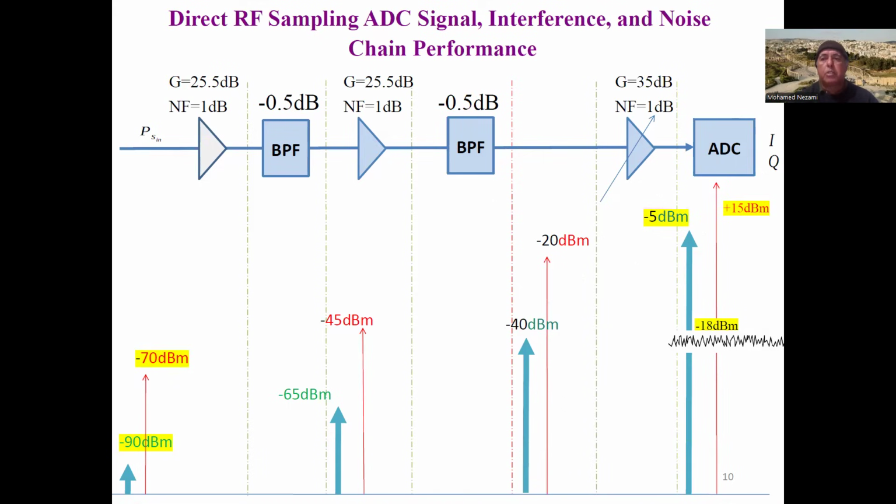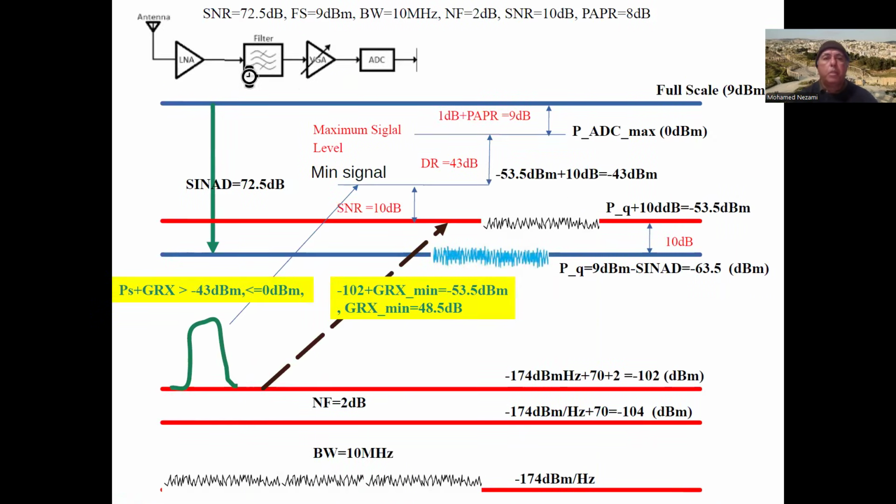because realistically the ADC that you're going to be using is an interleaved ADC, so it will have these issues anyway. And of course, because the Nyquist frequency is so wide, you fold back the noise floor, additive white Gaussian noise, from the different aliases and the harmonics as well. But let's look at this again with this example. Let's say that we have this example with these parameters.